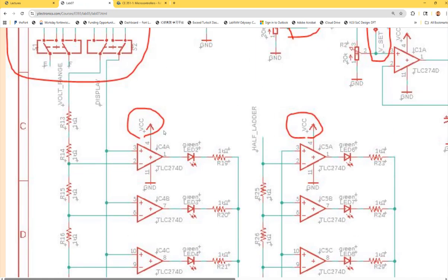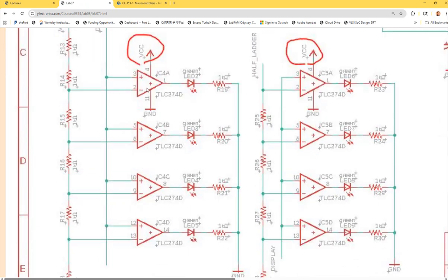I may have 4, 5 different ICs of the same op-amp, but I can see that all the 4 over here that are being used for the same purpose came from the same IC. So that chip has 4 op-amps in it, and if it's being used for the same circuit, you should use all the 4 from the same chip. For example, IC4 is that chip. It's A because it's the IC4's A op-amp, and then the second one is IC4's B op-amp, and then C, and D.